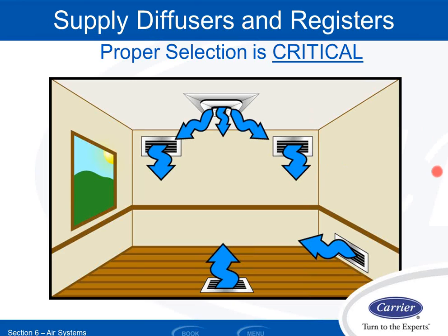Residentially, it is pretty good practice to have your supply air at the exterior also. So even though you got a floor-based system, I'll typically put the supply registers in front of the window to wash the window vertically up, and then I'll put the returns over on the interior walls typically. Right? I typically want to have the supplies and returns reasonably far from each other, so the air has to move through the space, which is what I really care about, in order to get back to the system.